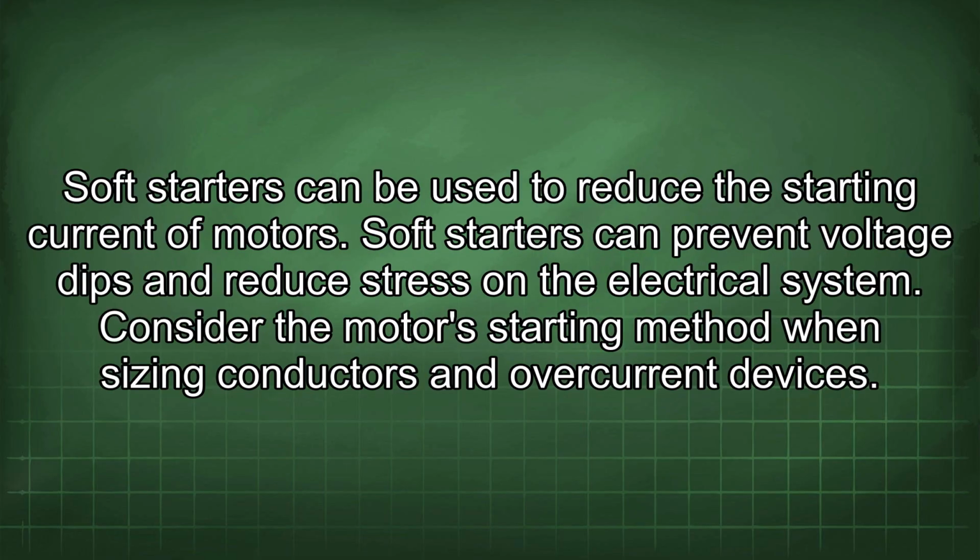Soft starters can be used to reduce the starting current of motors. Soft starters can prevent voltage dips and reduce stress on the electrical system. Consider the motor starting method when sizing conductors and overcurrent devices.